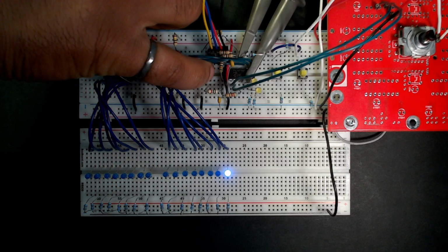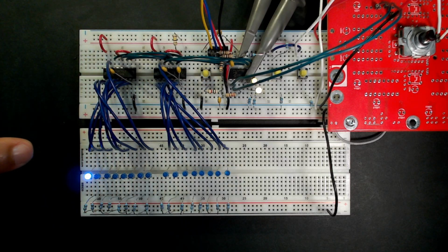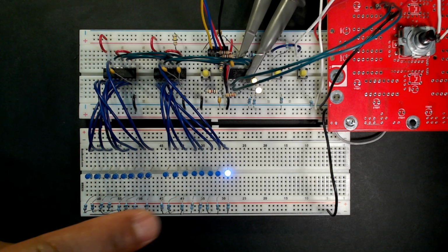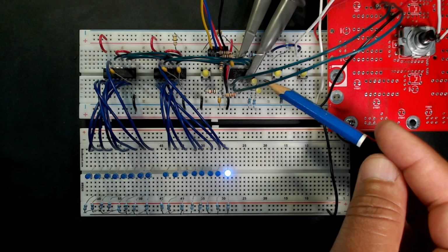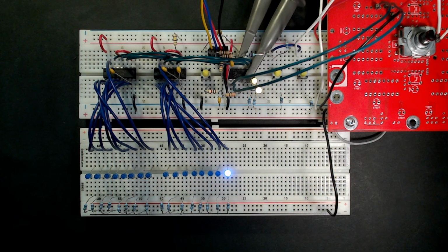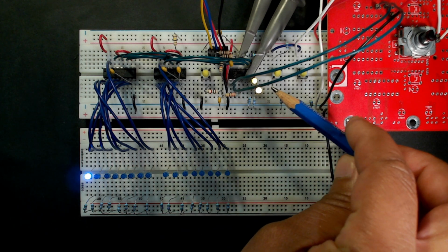Hit the reset, and oh, look at that. It holds for about 4 seconds and returns down to normal. That is perfect, and you can actually see the speed change of timer 0 by the LEDs that we have in place on the board. Remember, this upper LED right here is connected to the hardware out of timer 0. And you can see that LED slow down, and after 4 seconds, speed up.